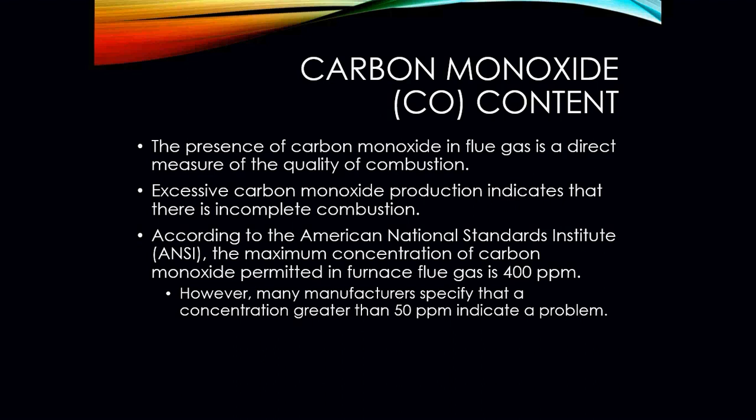Our carbon monoxide content. The presence of carbon monoxide in a flue gas is a direct measurement of the quality of combustion. Excess carbon monoxide production indicates that there is incomplete combustion. According to the American National Standards Institute, the maximum concentration of carbon monoxide permitted in a furnace flue gas is 400 parts per million.